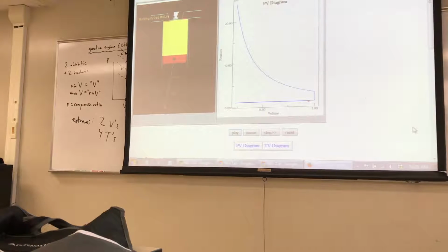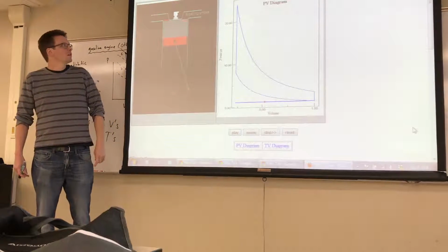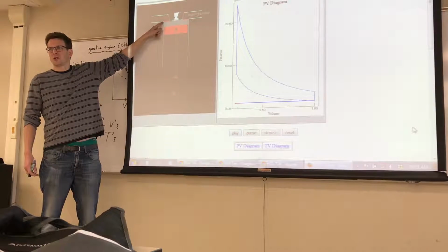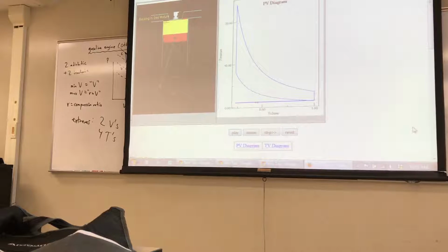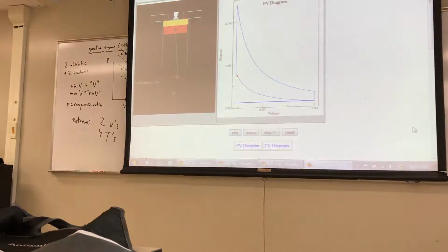Okay, so here we go from the beginning. Here's the compression stroke. We're compressing the gas, and we're causing it to go to a higher temperature. There's where we started. Then the spark plug goes off. That's the ignition. Here we go with the power stroke. That exploding gas drives it down. Now that the gas is expended, we've got to get rid of it. So we expel the smoke, and we take in some fresh new mixture of unspent fuel. Notice that's a whole extra trip up and down again. You have to expel the old burnt fuel and get the new in, but that's happening outside of the PV cycle, because you're just pushing spent warm exhaust out and pulling in new fresh stuff.